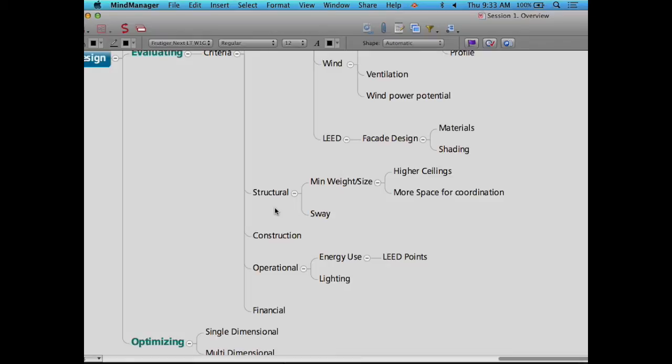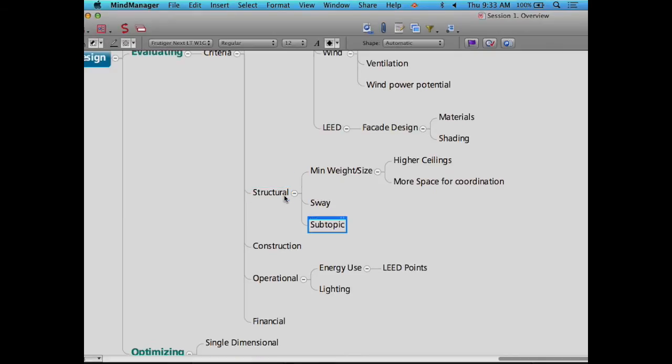And that's another one of these things that is actually a designed consideration. As we do houses, deflection, we always have this debate: do we want to use L over 360 or L over 480? It's really just this funny notion of how springy things are, and it gets to people's comfort